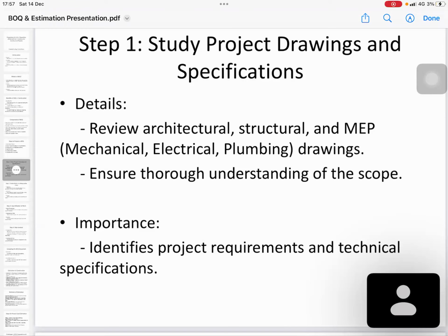Sometimes some requirements are not in the drawings or specification. Then you have to go to the relevant parties and have a detailed discussion, minute it somewhere, and come back and put it into the BOQ. Remember, for anything not in the drawing or specification, it is better to call a meeting among the required stakeholders, do the proper minuting, and come back and put it in the BOQ.